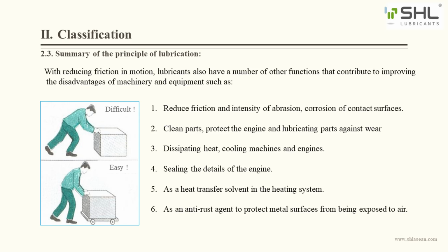good quality. Specifically, the lubricating oil must have good adhesion and must be suitable. It must have good chemical properties, good biomechanics, good heat conduction, no chemical corrosion, and good cleaning and dispersion of soot deposits generated during the use of engines and equipment.